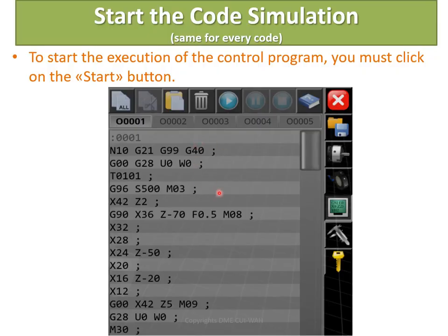So far your coding is complete, your program is complete. Now we have to run the simulation for checking if any error is there, so we can be notified. There is a play button. From here you can run the simulation. So if there is any error, it will be notified. As discussed earlier, before working, we will run the simulation for checking the error.